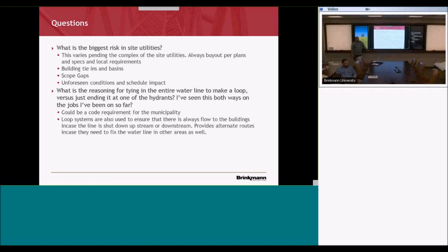I got an underground detention basin for about $10 a cubic foot, and it's a little over 6,000. What kind of detention basin? Underground detention basin, this is for that Morgantown job. Okay, so Morgantown was like a modular grid poly system. There are those types of systems, there are pipe underground detention systems, there are concrete vault box detention systems, so there's a multitude of underground detention systems.